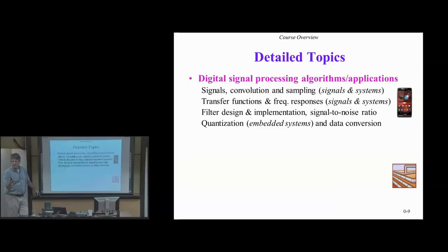What was the data converter in the 319K class? How many bits? 4 bits? I think the DAC was 4 bits. The ADC was like 8, 10. Right, so the analog to digital converter was 8 or 10 bits, and the digital to analog converter was 4 bits. Okay, so we built it with an R2R ladder. So you really know. Good.